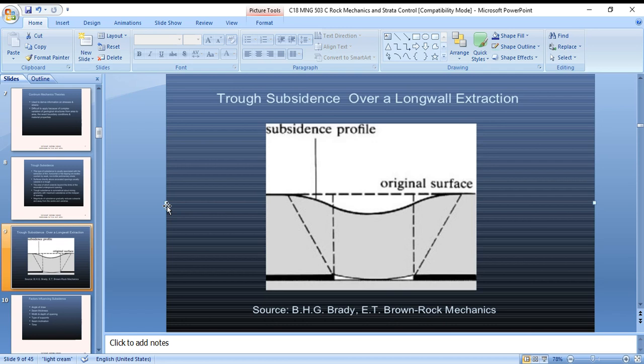The angle of break depends on the angle between the vertical and the line connecting the limit of excavation to the point on the surface. The maximum tensile strain point A is where the line passes through the point of maximum tensile strain on the surface and defines the planes of break. Although the strain may not be large enough to cause a fracture for any given rock type, this line is assumed to be straight, although there is some evidence to indicate that the slope increases with depth.